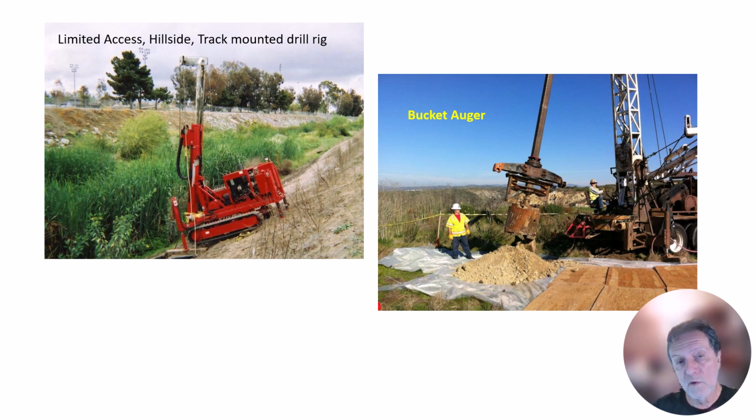wide diameter hole, 24 inches to 30 inches in diameter, that you can actually lower a geologist down that hole in a steel cage, hopefully, and look for any features of landslides such as slide planes, distorted bedding, and that kind of thing.